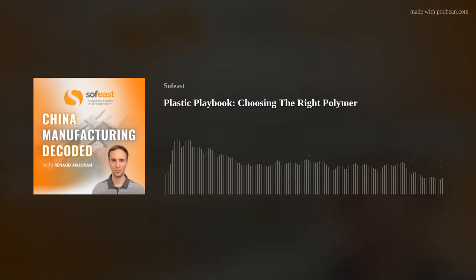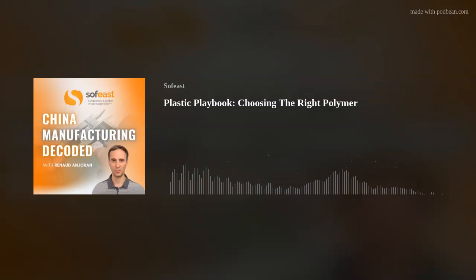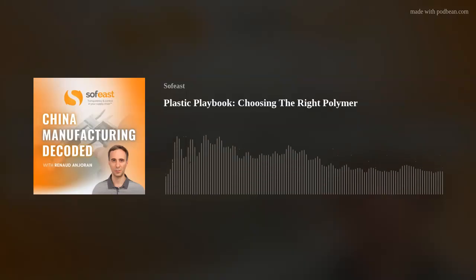This third component is not sticking, let's say, to the polypropylene, whereas it used to stick to the ABS, no problems. All of the tests and everything were done on the previous version, which was ABS to ABS, and everything was perfect. But now one component was being put to the test because it wasn't sticking. So we had a major problem, and we still had to go through the root cause analysis.